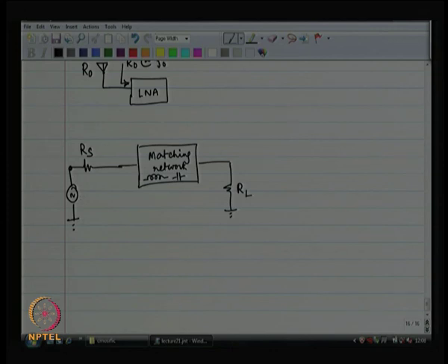All right. So, I have to choose whether the impedance transformation is going to go upwards or downwards, and accordingly I would have to choose the L shape in a certain fashion, right. So, I would either have to have a series L and RL, or a shunt L and RL, and accordingly I would figure out what the matching network needs to be.